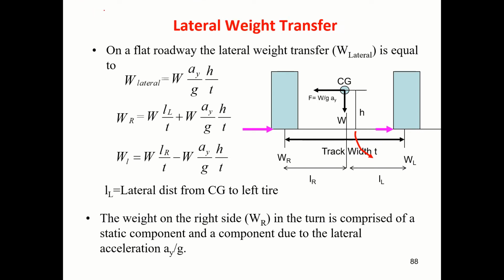Earlier, in the longitudinal acceleration, I derived the load on the front as the static load plus W by g, a x h by L. This I called the dynamic load.